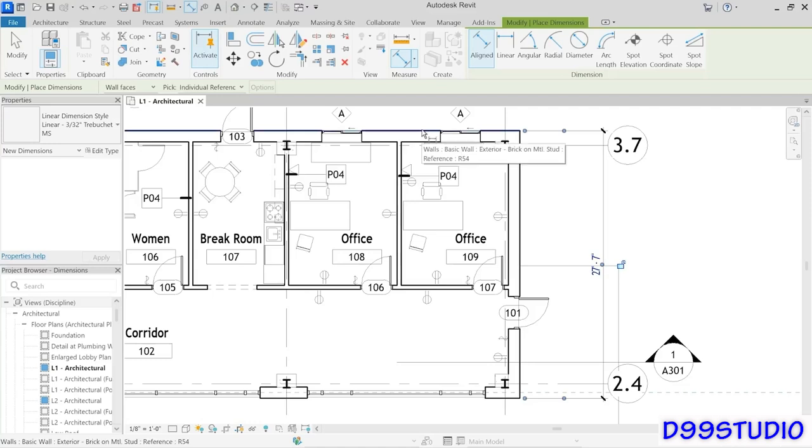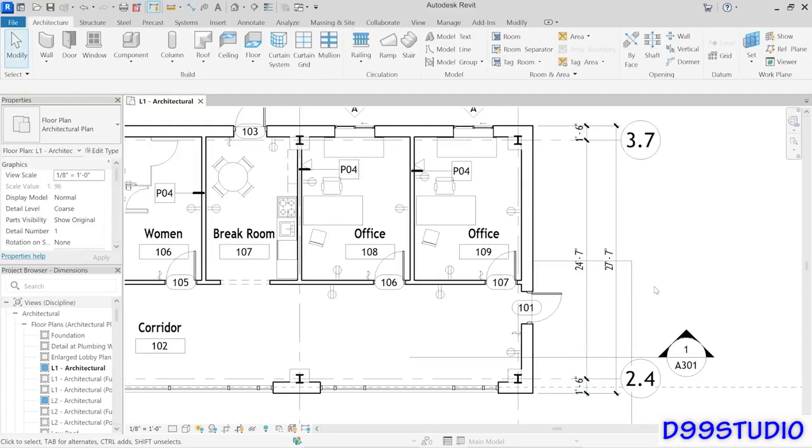So if I pick the same start point on this exterior wall, and then this time include grid line 3.7, come down here and include grid line 2.4, and then finally the exterior wall here, you can create a dimension that includes as many witness lines as is necessary. Now, as you move around here before placing it, you should sense a location where it wants to snap. So there's a built-in offset in the dimension type itself, which will keep them spaced nicely relative to one another. So you can just sort of click when it snaps to that location.